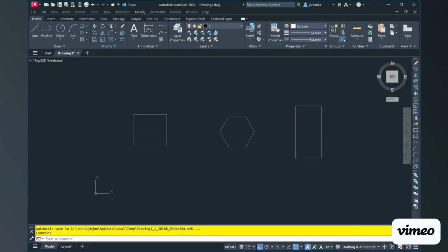So we understand already about the offset command, but now we can use this offset command to make not only our objects offset each other, but we can already have them set as fillet line segments or even chamfer line segments. And we can do this by entering simple values.